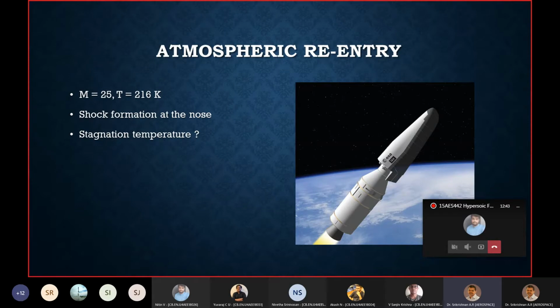So hypersonic to supersonic as opposed to hypersonic to subsonic. Because of this difference, you will encounter less increase in temperature and less loss in stagnation pressure. So that's the reason.